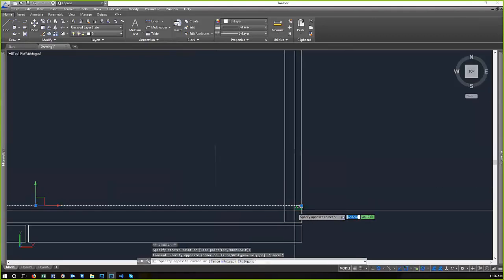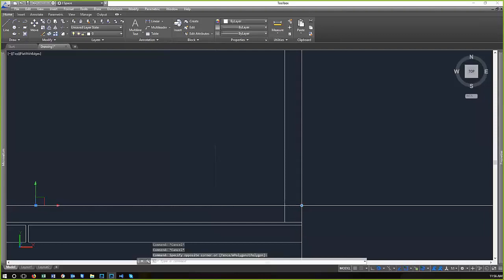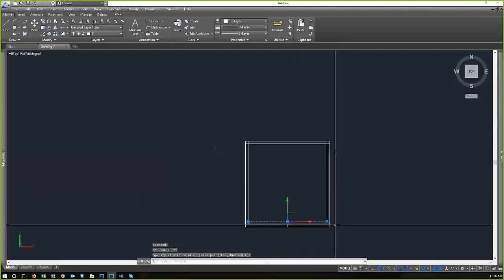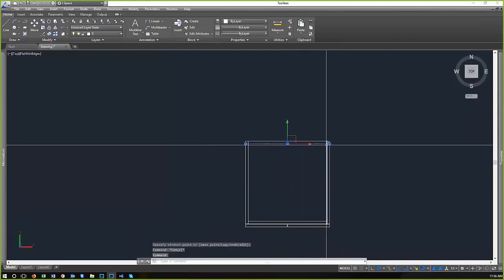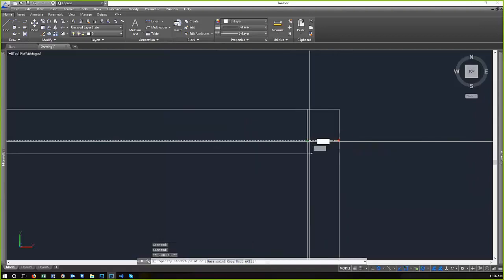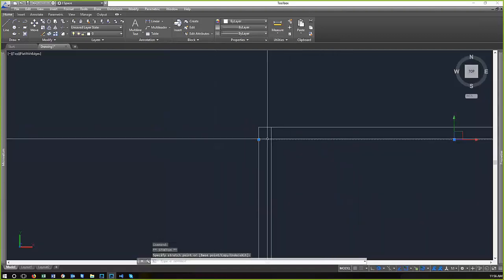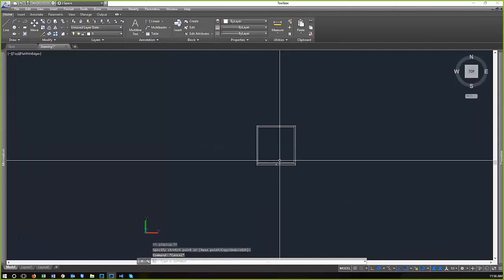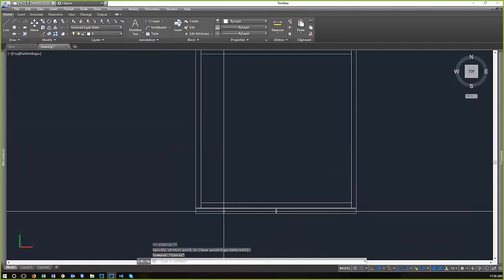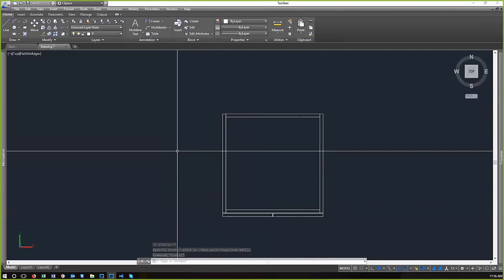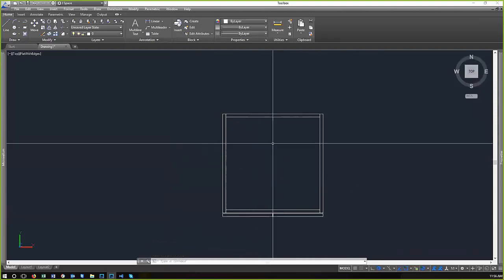So we'll show you another way later. It's a bit faster, but for now, you can just drag these lines in using the grip points, and then you have a fairly accurate, we don't have any internal components, but we've got your doors, you've got a basic plan section of a cabinet.